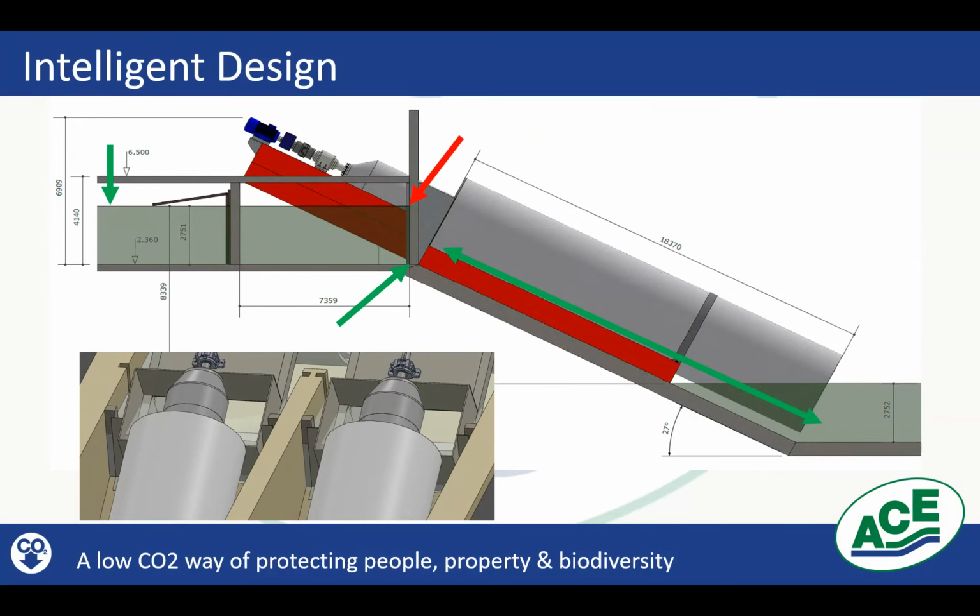Our Archimedean screw pumps are different because they have a completely encompassed rotor which is sealed within the drum. So the whole drum rotates, the helix that goes throughout the drum is completely sealed, and what that means is that water cannot run back from the screw. Every drop that goes in comes out at the top. It's impossible for any run back to happen.